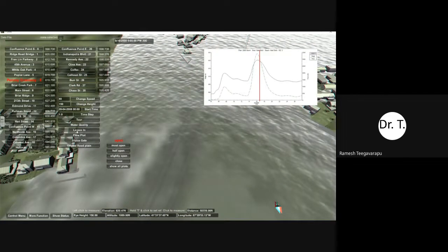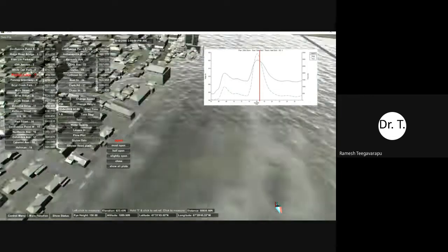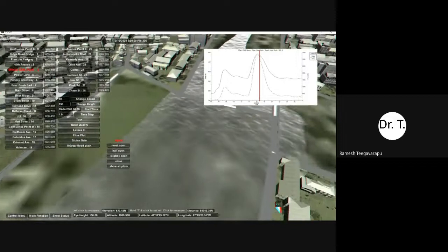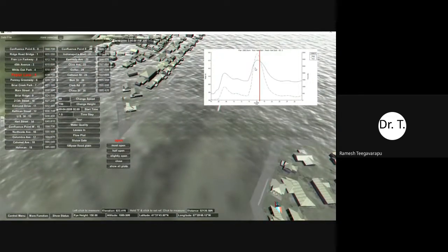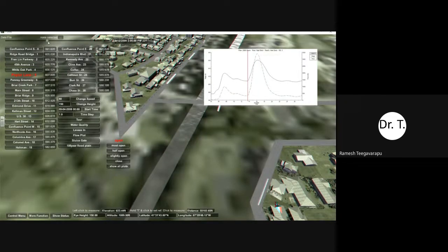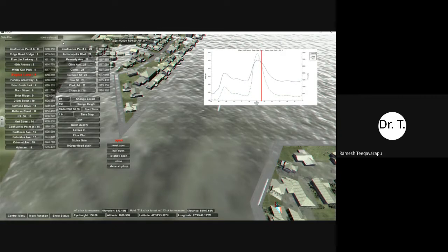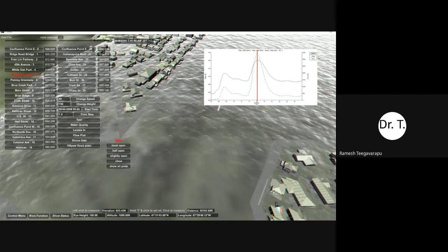This one doesn't have the levee system on, and you see that a number of houses are flooded, and you can appreciate how much water is coming to it because of that. If you go ahead here, you can see the extent of flooding, where if I were to move the hydrograph simulation, slowly, suddenly, the water level is going up and then starts filling up, and then it recedes as the hydrograph recedes.